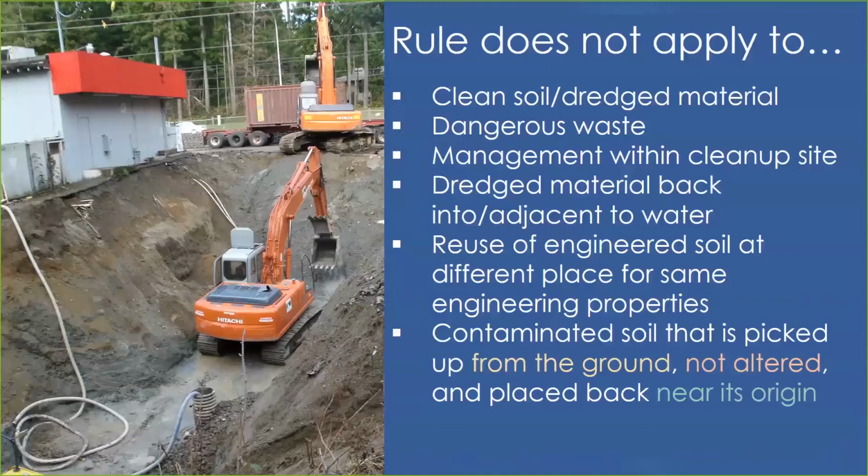So I do want to say that the rule doesn't apply to several activities, and a lot of these are all excluded in the applicability section of the rule. I did talk about them earlier, but I'm not sure everybody who's interested in this section was on early today. So materials placed in ways that obviously meet the cleanup rules or pH standard for placement is considered clean soil or dredge material management, which is not a solid waste handling activity. Anything that might designate as a dangerous waste is not captured under this rule at all. Our hazardous waste regulations apply to management of things that have contaminant limits at those levels. So this rule is only for solid waste management.